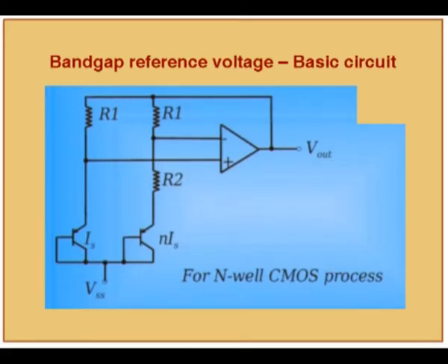There are other things like when VDD scales, this op-amp should be able to handle this node voltage. So the common mode input range of this op-amp should be such that it can handle that low voltage here. That's why the design of this op-amp at low voltage is also not very straightforward. So there are again different methods. What they do is use a resistor division here to change the voltage here.